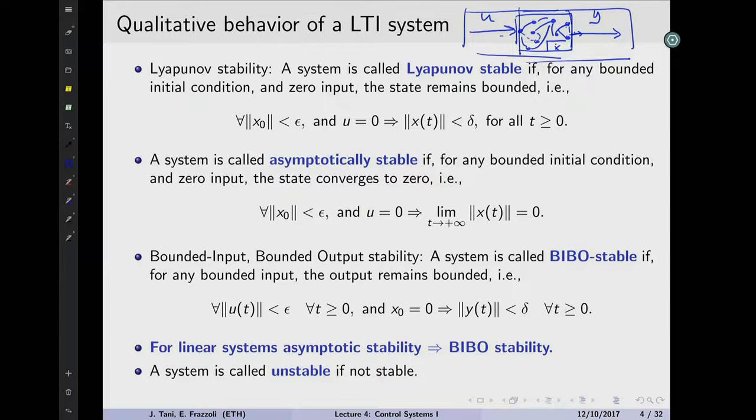If I set an initial condition to be something reasonable, something that is bounded, not infinite, and I let it go, then if the states vary within a bounded region of some finite number, then we call that stable, right? Imagine a pendulum in a world without friction. You let it go, and it continues going back and forth forever. But it's bounded. It will never go all around. It will stay within the bounds given by the initial conditions.